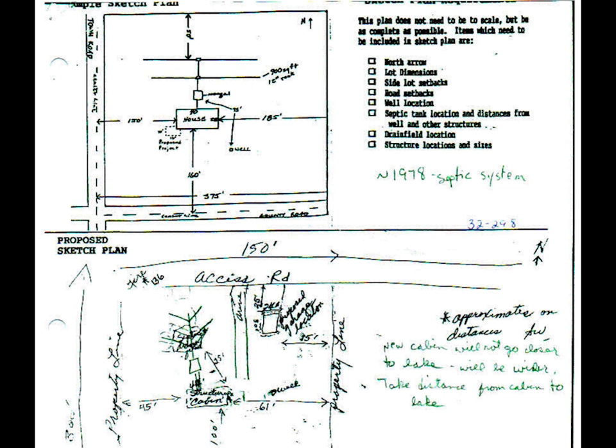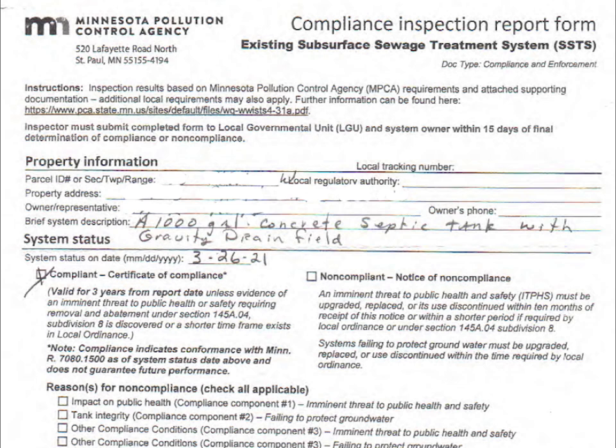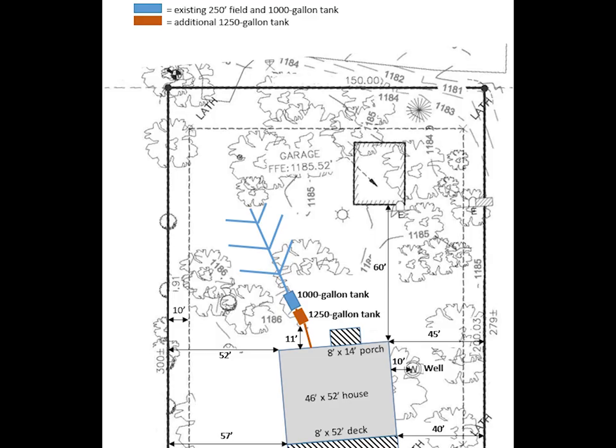passed inspection. There's an additional required test that sees how quickly the soil can absorb water, not too much clay or other impediments to water transfer. This is known as an absorption test or a percolation perk test. My field had no issue passing that test. As per our discussion above, we had the existing 1,000-gallon tank. We needed to add to this a multi-compartment tank of 1,250 gallons with an effluent screening device.